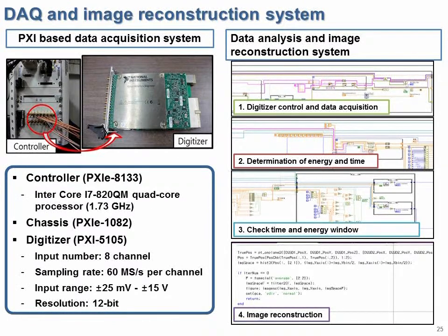We developed a DAQ and image reconstruction system. Using the digitizer, we converted detector signals to digital signals. With the data analysis program, we determined the effective events in energy and time window and reconstructed the 2D images using the line back projection algorithm.